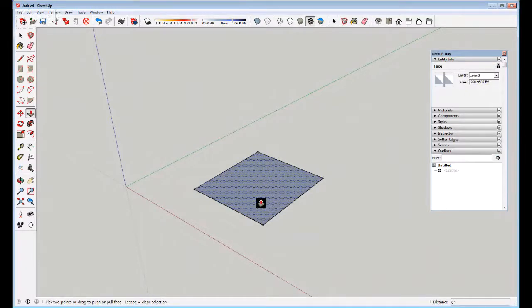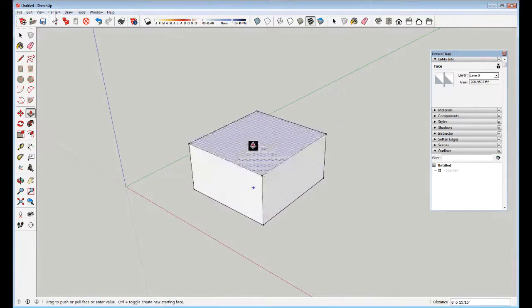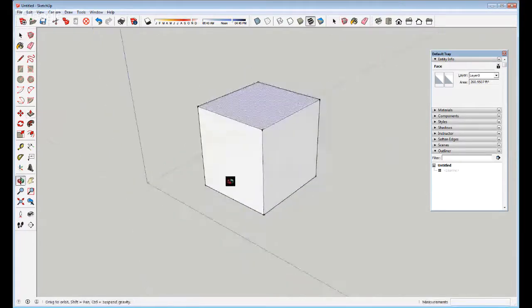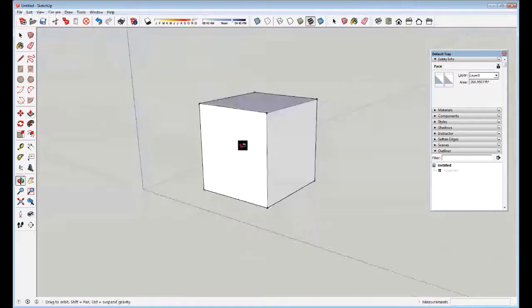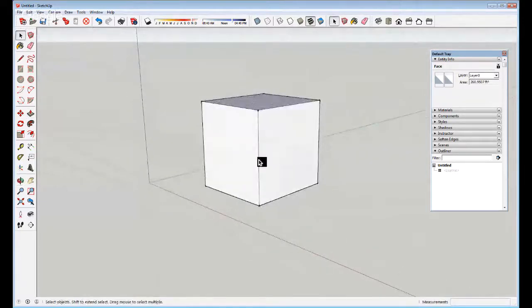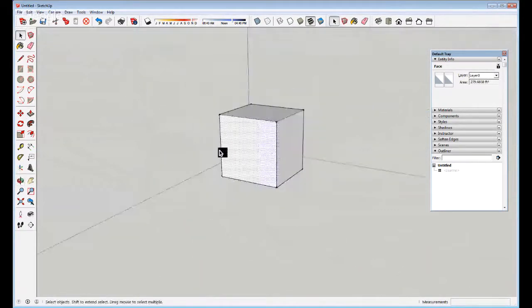So what we have here is the Extrude Tool. You can find it over here. It's called push-pull, but basically what it's doing is it's taking a plane and extruding it in one dimension or in the other. And what it's going to do is pull the face up. And as it does that, to whatever increment that you want to, it will create the other sides of that